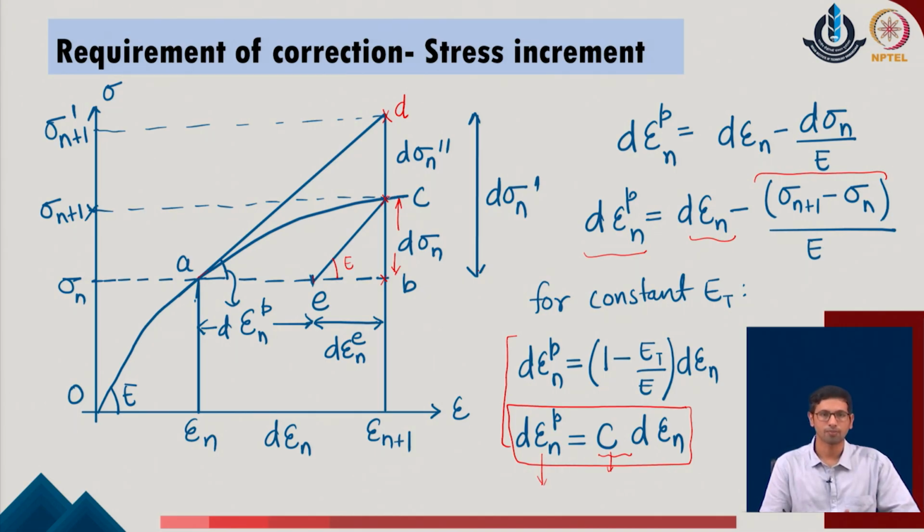So, using this idea, the user can now identify that for a system in which plastic strains are introduced, and in which the elastic modulus changes regularly and continuously throughout the nonlinear range, the effective value of the plastic strain can be defined by this relationship. Or in case the elastic modulus in the nonlinear or plastic range becomes a constant value, which means it follows a more or less bilinear kind of profile, we come up with a simplified form of the expression to give the plastic strain parameter of the given system.